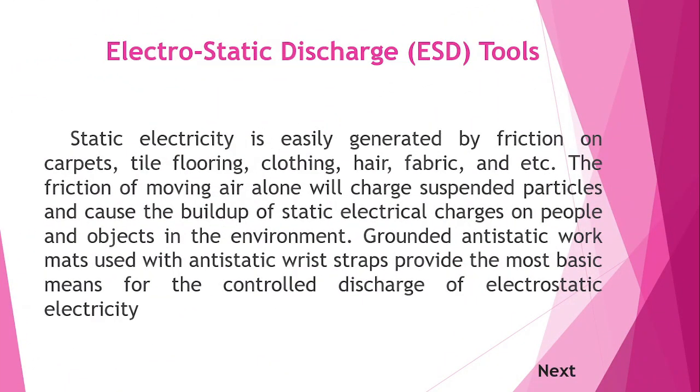Electrostatic discharge tools. Static electricity is easily generated by friction on carpets, tile flooring, clothing, hair, fabric, and etc. The friction of moving air alone will charge suspended particles and cause the build-up of static electrical charges on people and objects in the environment. Grounded static work mats used with the anti-static wrist strap provide the most basic means for the controlled discharge of electrostatic electricity.